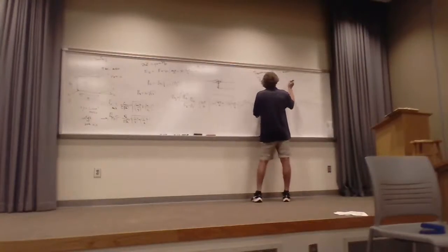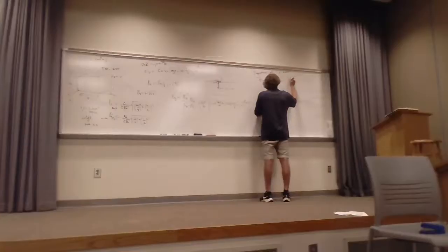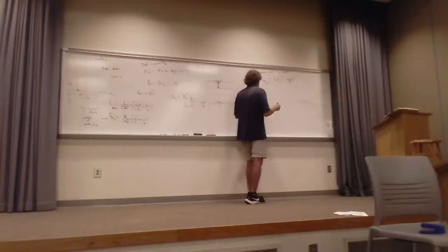And that's going to be equal to, and he calls this eta unguided, times square root of 1 minus the quantity f_c for the given mode over f. That's the actual frequency of excitation.